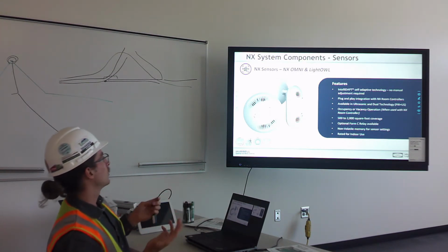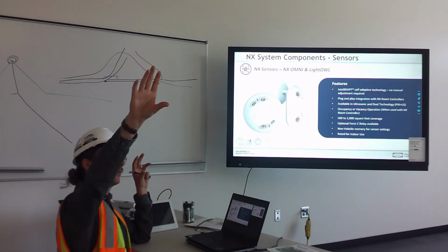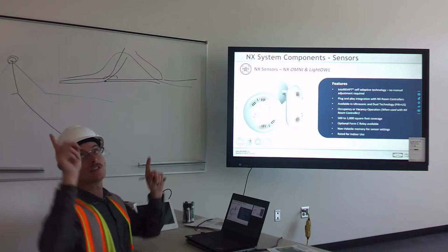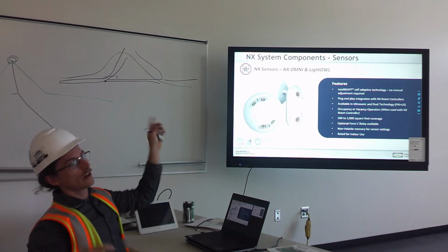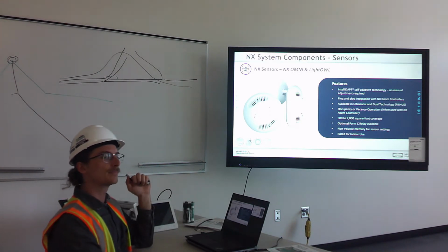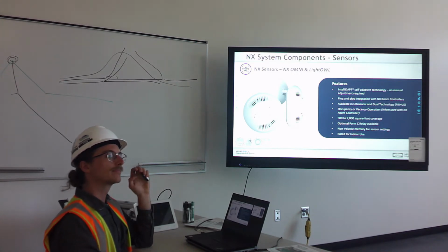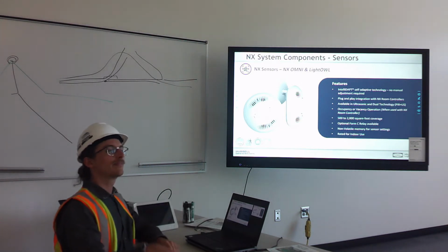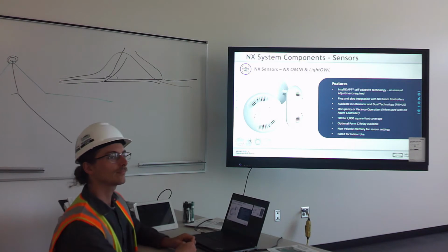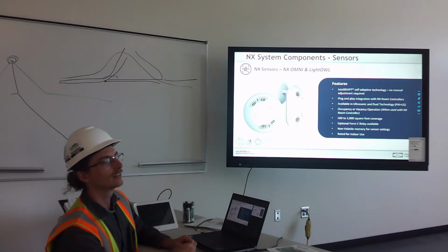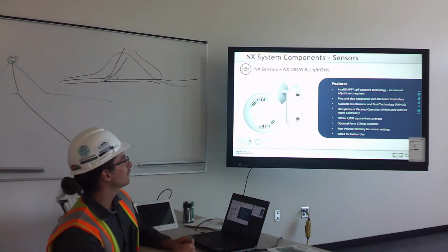In some situations, you might find the sensor is kind of far away. We have that motion problem typically in all our schools. I don't see it happening here because we have two sensors in 361. This room actually has two, but most of the classrooms only have one. In most of our older schools, most of the classes have one in that far corner. They all come out of the box set for both, and when the teacher's in the room by herself in the morning, she gets put in the dark. So we always have to go in there and change it from both to either.